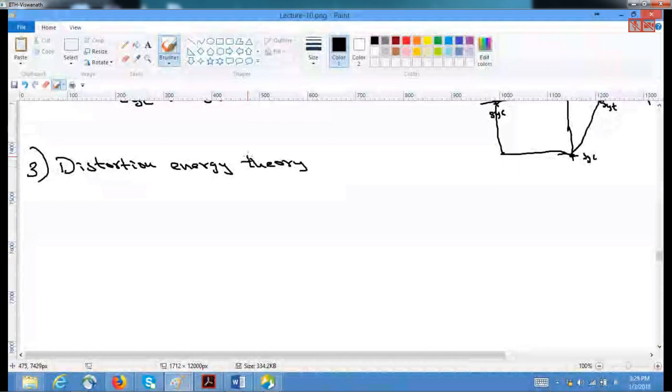So in this, okay, if you have a spring, right, force is given by K, the energy stored is nothing but the force multiplied by the displacement. Force into displacement, and since it is in a quasi-static manner, it is this 1/2 K x square.